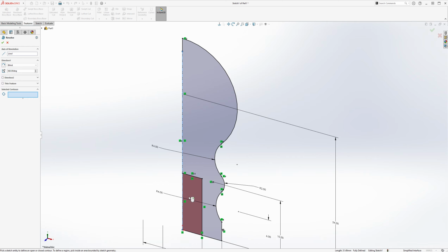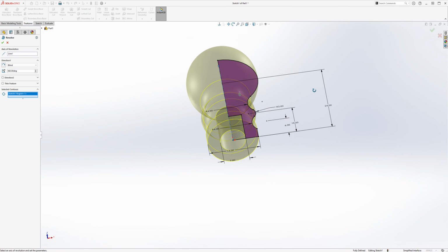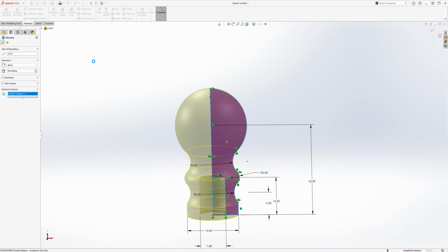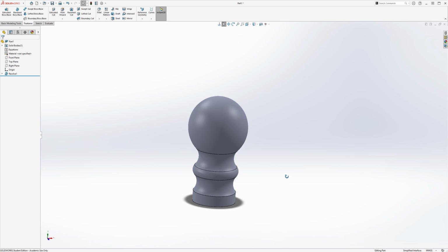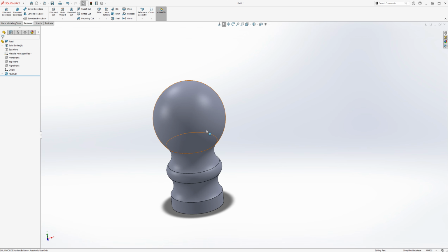Okay. So you didn't actually have to get rid of this line. You could just keep it, but just not select the contour. Just select everything around it, and you'll get the hole in the middle. Okay, that's perfect. So you check mark, and there's the hole. Perfect. And all I need to do is just add two perpendicular circles, or holes, I mean.